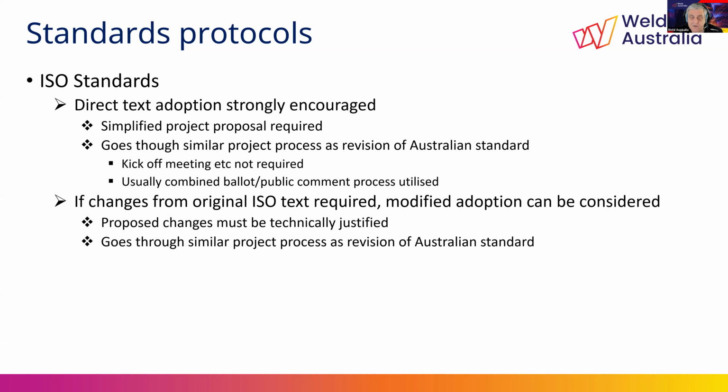On the flip side of this, though, some excellent standards have been adopted, including the ISO 3834 series, which in Australia is the AS/NZS ISO 3834 series. This is a very logical and practical series of standards, and it applies primarily to ensure that weld processes are under appropriate control and the procedures being followed are reproducible at all times.